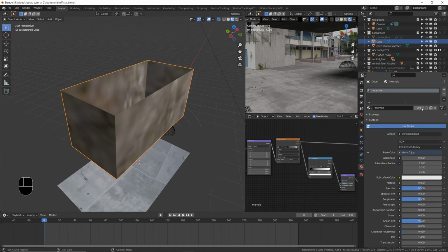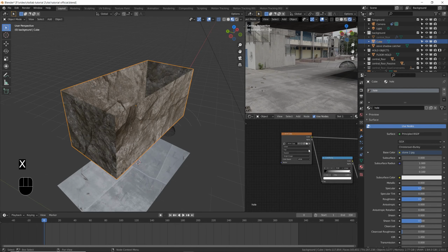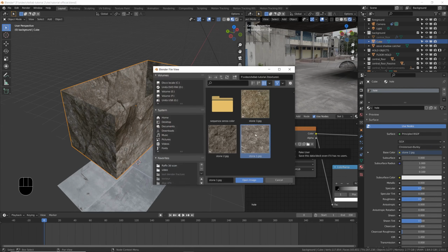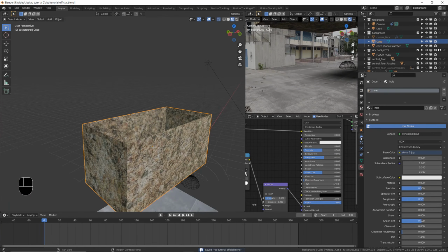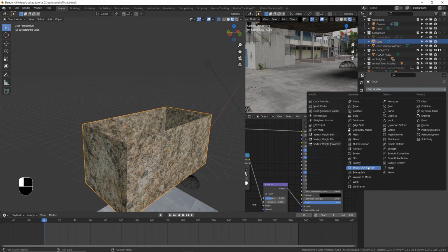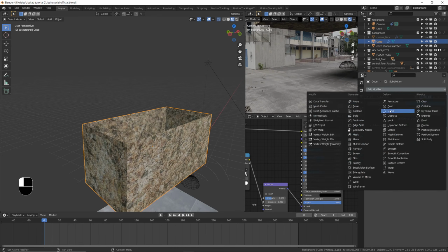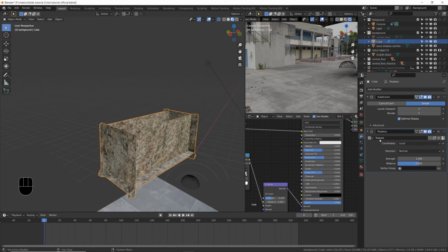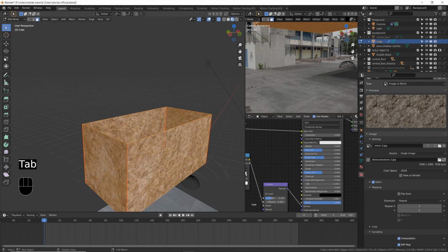You see this high number indicates the number of objects that use this material. I'm gonna make a copy of this material, and this is gonna be the hole. We don't need these nodes. We can actually change the texture if you want. We can put something like this. And we can also give this a displace like in the rocks. So subdivision surface, simple. I'll set this on 3, and displace modifier. This is gonna be a new texture. I'm gonna call this hole, and going to the texture properties, I'm gonna choose our stone 2 texture. Subdivide this a bit.